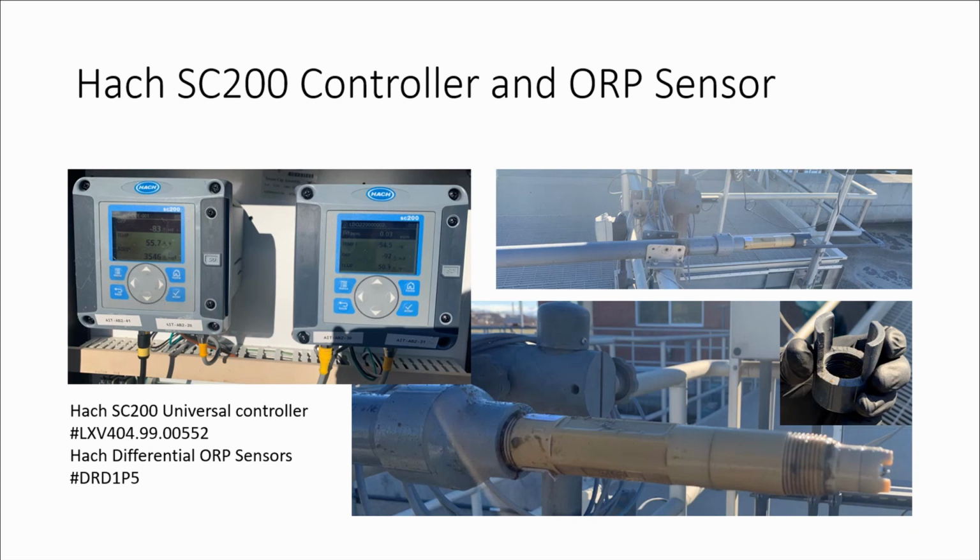You can see on the very bottom, there's a little silver dot sticking out on the end of that probe, and that's a platinum tip. And what we had was, while people were calibrating, they were sticking the probes into the cal bottle, and they were actually breaking those tips off. Okay. So we built, and all it is just a shoe.